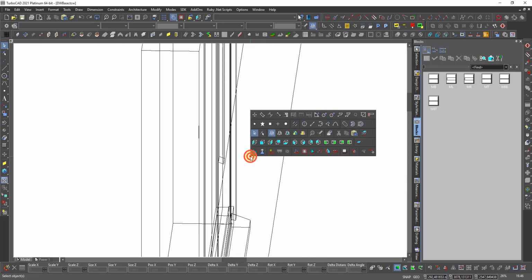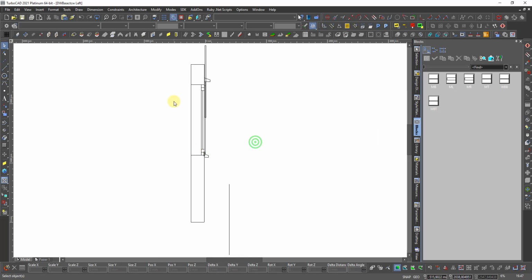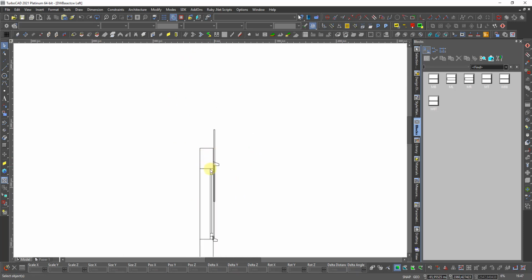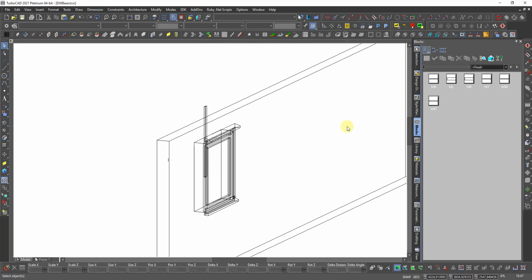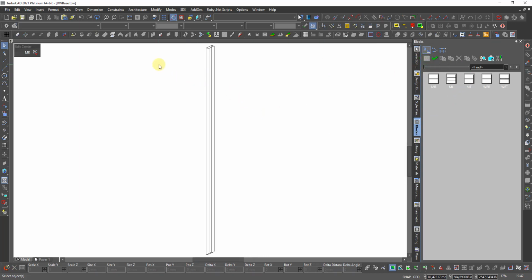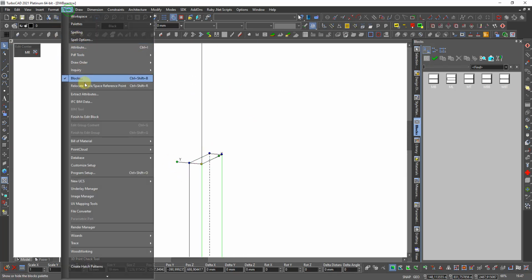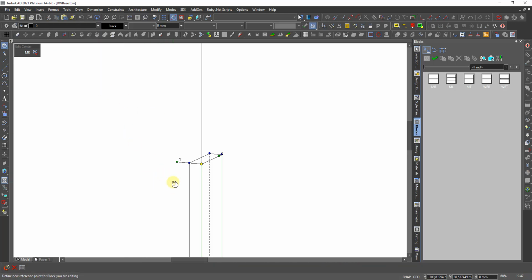It seems to be outside also. Yeah, only it's a half distance wrong. Don't care about the reference point. I can go in and reset the reference point. I take this. It should be here, and I can go to Tools and relocate block the reference, and it turns up this big, little bit big yellow dot there.